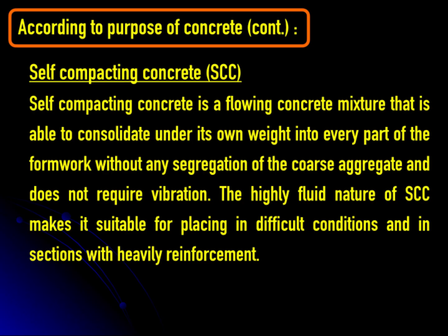Self-compacting concrete, or sometimes called SCC. SCC is highly flowable concrete and can be used to fill complex formwork under its own weight without vibration. It is suitable for areas with dense steel reinforcement or complicated shapes.